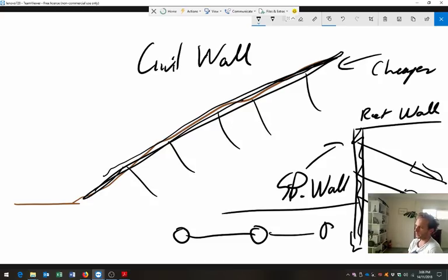So there's no real, there will be a practical limit, but there's no technical limit on how long your precast pile can be installed, because we can keep adding more and more piles on top of each other as we go in. I'm not certain about what you mean by the beam, but yeah, the precast pile lengths can be really quite long.